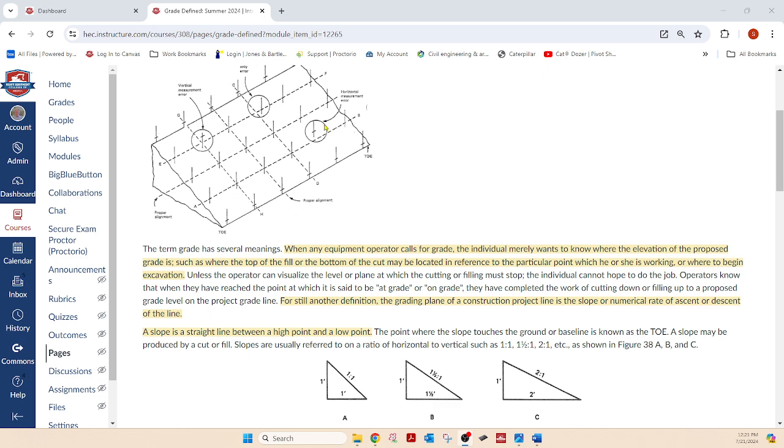But you'll end up with a slope. You just have to cut the steps off of it. And this will be how things are staked. These first stakes are staked first. Imagine that. And they're called toe stakes. We're talking about a fill slope here, not a cut slope.